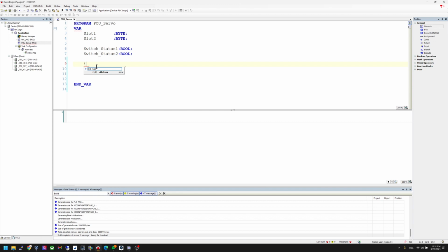It is very useful because I would not prefer you to map the data directly to the hardware, because if you change the hardware or have any modifications, you need to change everything inside your program. But if you have a buffer, you only need to change the first line, which variable is assigned to that buffer.